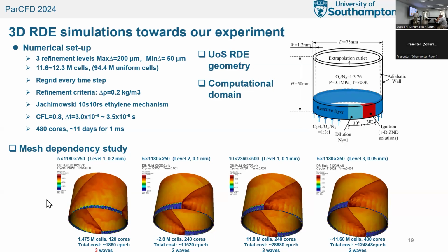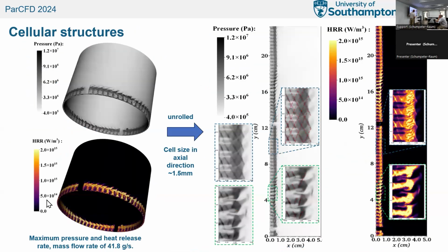Yeah, and then you see the convergence. It actually is somewhat converged. And when we have that high resolution, we can actually make visible these detonation cells. These multidimensional cellular structures would come into being also in such RDE configurations, and making them visible in a 3D configuration is actually an accomplishment. Very few people have actually done that. And here we are showing these detonation cells.